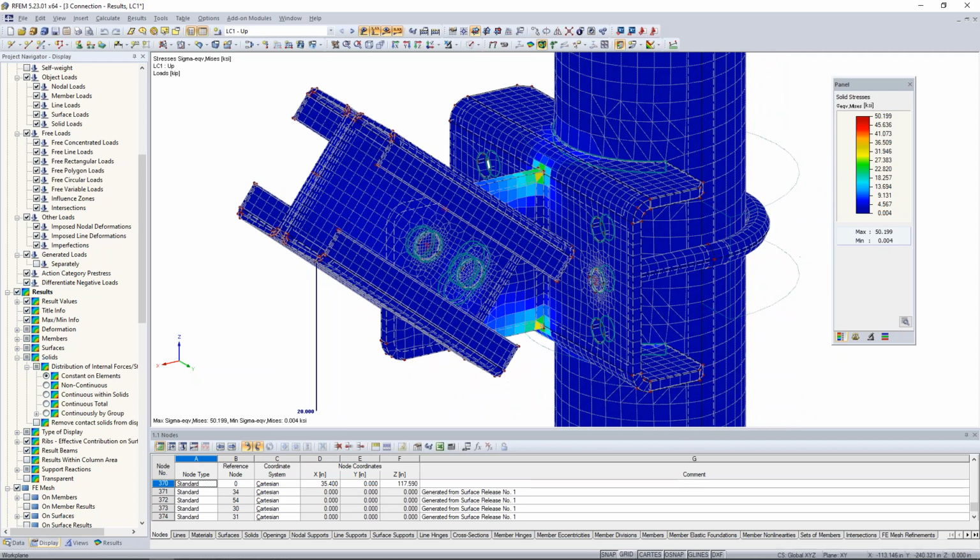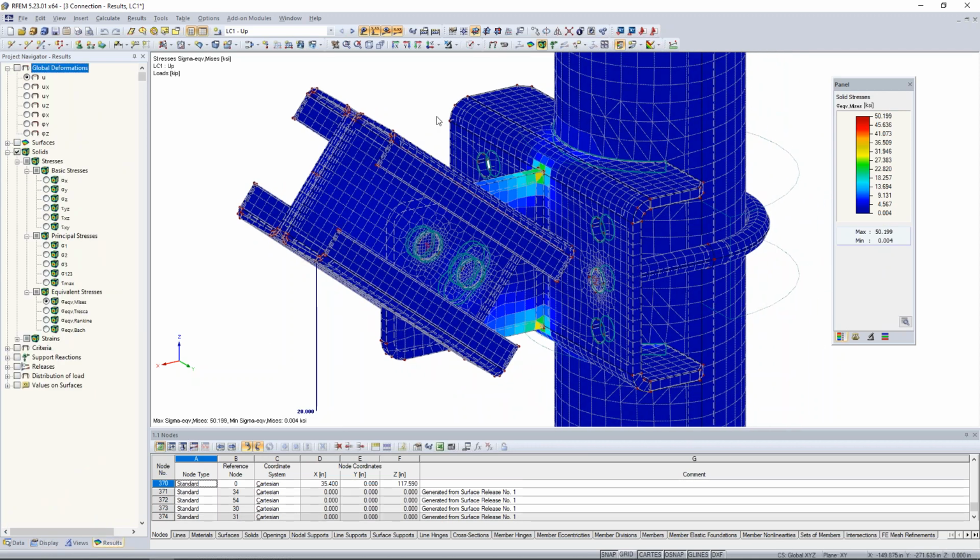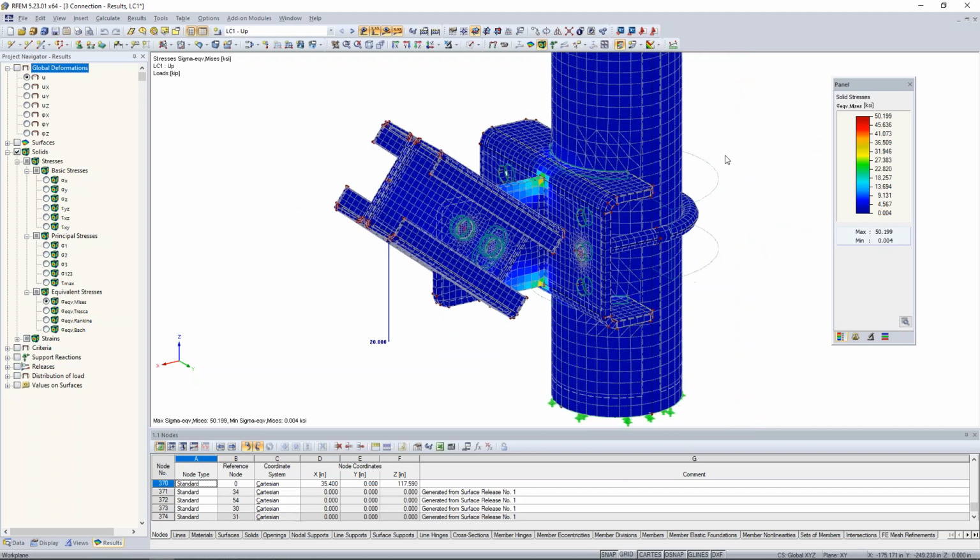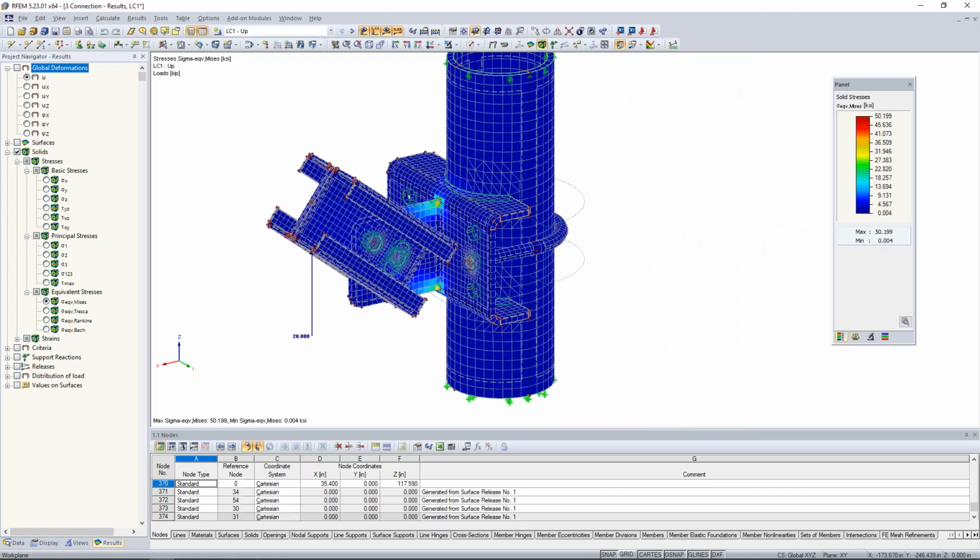Well, with von Mises stresses this high, I think this would immediately flag us that, okay, we probably need to run some type of plastic analysis. Remember, the material for these two plates is A36, so our yield strength is only 36 KSI, yet we have stresses clear up to almost 50.2 KSI. So what we'd like to do now is to take advantage of one of those nonlinear material models that we discussed back in the PowerPoint.